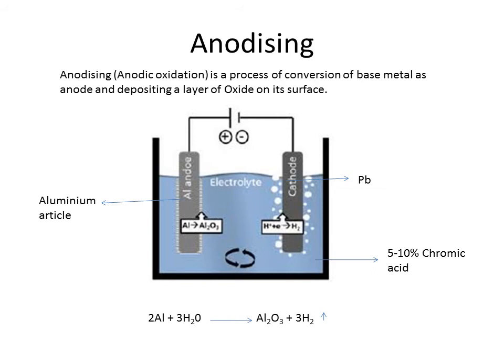Now we will discuss the last method of corrosion control, that is surface conversion coating. In the case of surface conversion coating, the surface of the metal to be protected is converted to its respective compound, and that compound acts as a protective coating on the surface of the metal. In this case we have the example of anodizing. Anodizing is nothing but anodic oxidation.